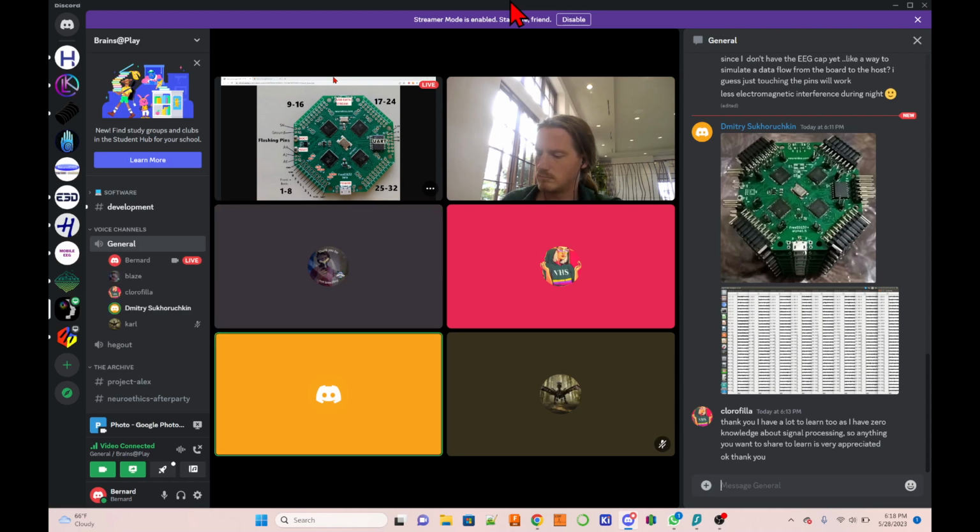To the head, I also use pogo pins with gold, and also add gel. The pogo pin with the springy part connects to the head, and it's not painful. It's a connection of gold to skin, and also gel. So it's not a dry electrode, but with gel. And I placed these electrodes,